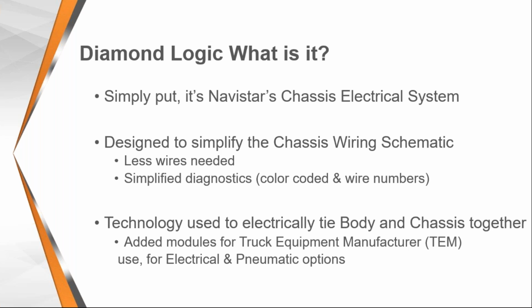Nowadays, we can simplify that and have those switches talk on a datalink down to our body controller, and it will disperse that information down to an output or another module to force an output. So the wires are smaller and there are fewer of them. All of our wiring diagrams have color coding, or should I say the wires are color coded, and our diagrams depict that.